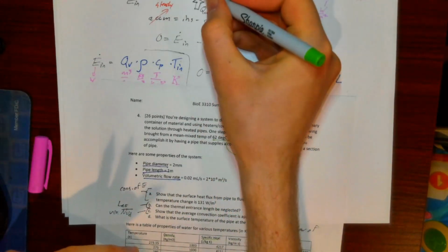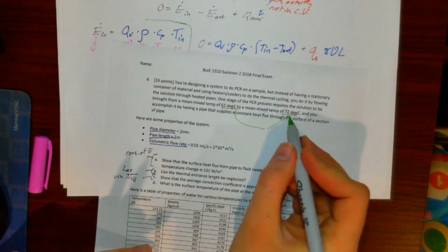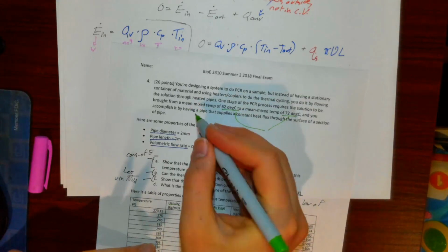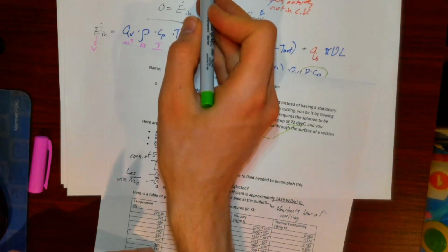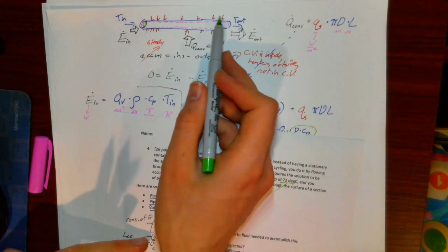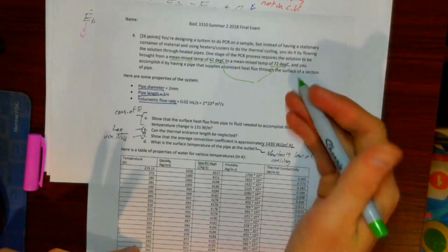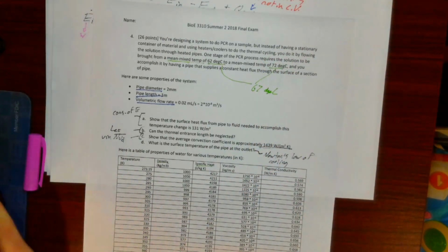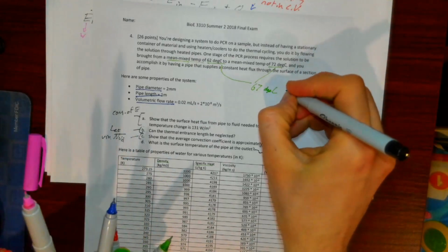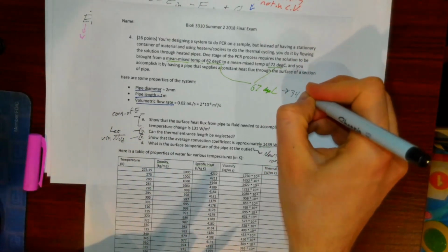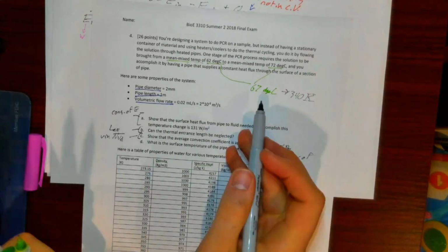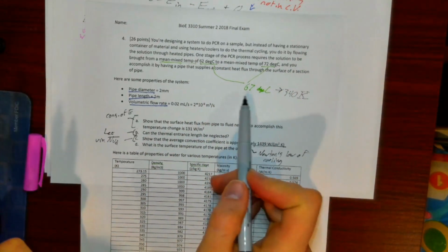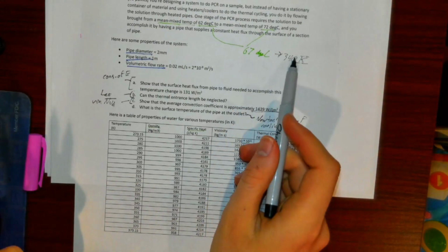So, on average, or somewhere in the middle of the pipe, I'm sort of taking averages of averages, right? These are essentially averaged across the cross-section, but I also want to average over the length to get one single temperature that describes, for the most part, what the temperature of this fluid is. So I can basically say, hey, I'm just going to average these two, so I'm going to use 67 degrees C. And of course, we got to translate to Kelvin. There's that 273.15 difference between degrees C and Kelvin. So we add that to 67, and it ends up being 343 Kelvin.